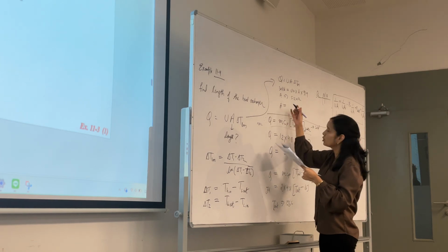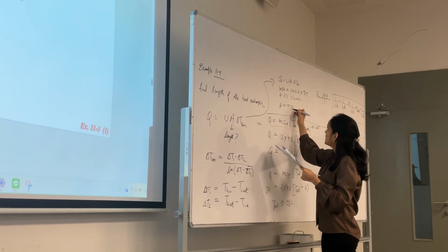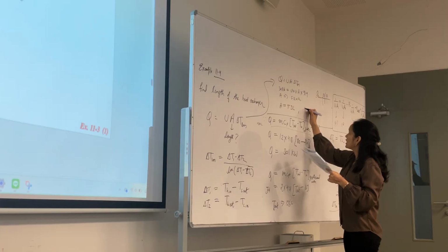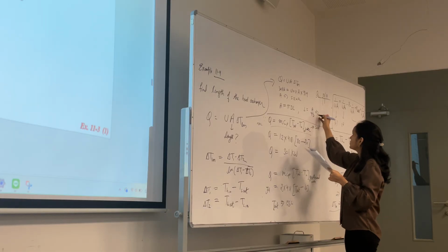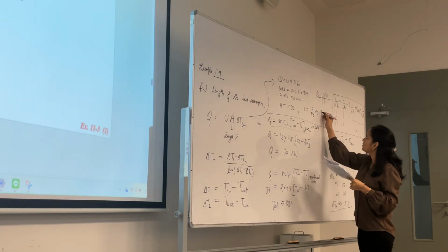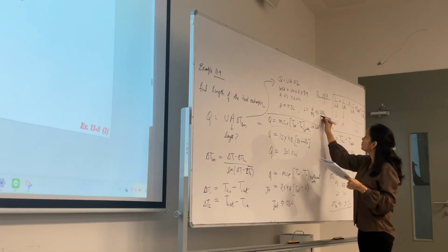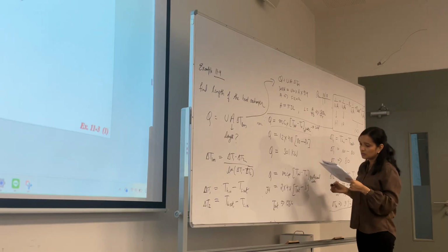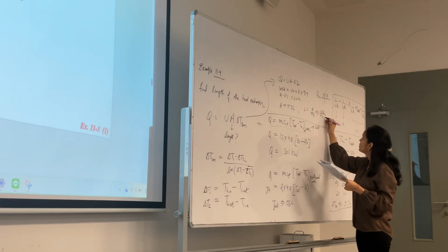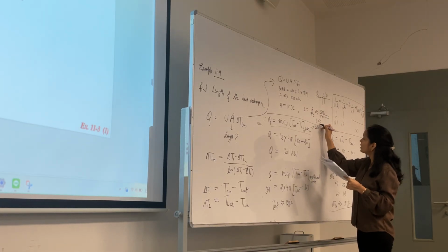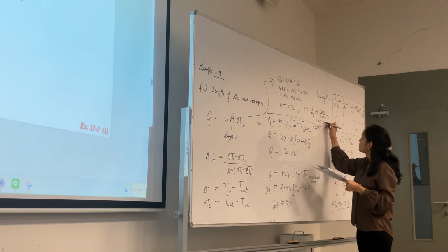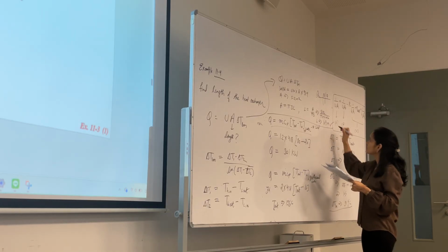It's a cylindrical tube, right? Area is pi d L, so we can calculate L. Diameter is 4.215 meters. So from here the L will be 109 meters.